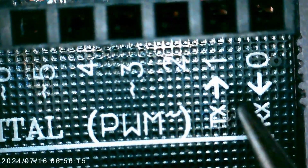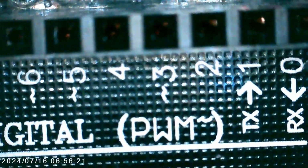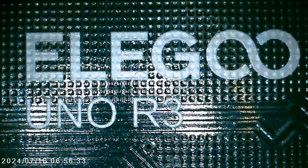And then over here, let's flip it over, these are the digital pins. It goes from 13 to 0, so there are 14 in total. The ones with the squiggly lines in front of them, like 3, 5, and 6, those are PWM. And then at the very left, there's a ground. And that is the showcase of Elegoo's Uno R3 board.